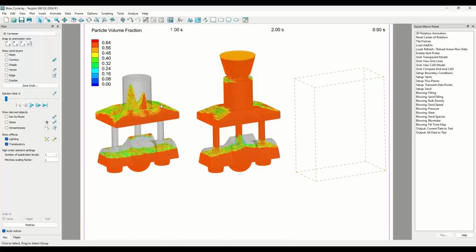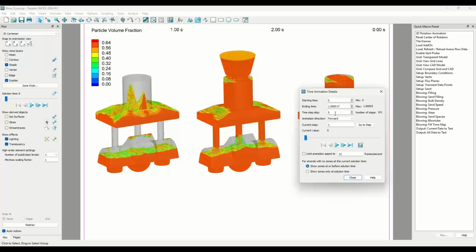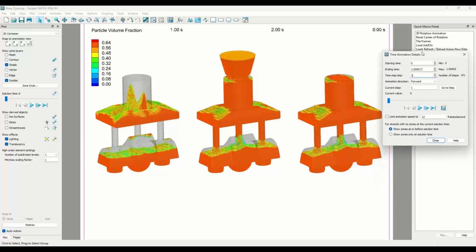So now that's great, right? We established that we got enough sand in the magazine to actually restart a calculation. A second blow. Let's see again. So I removed the hopper, but here we are. We have a core that's half full. We got something that's dropping down. So let me go back and change the time step. And we can play that.